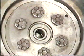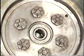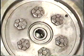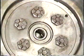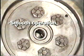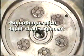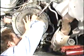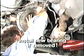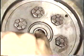Finally, check the pilot bearing. The end of the input shaft is held in place by the pilot bearing, which allows the flywheel and the input shaft to turn at different speeds during shifting, but still maintains proper alignment. It's important that the pilot bearing operates smoothly at high speeds, otherwise the bearing may be noisy. It could also allow the input shaft to move out of alignment. It's best to check the pilot bearings in place because once they're removed, they must be replaced. These bearing rollers look okay. They're rotating smoothly and the bearing is firmly seated.